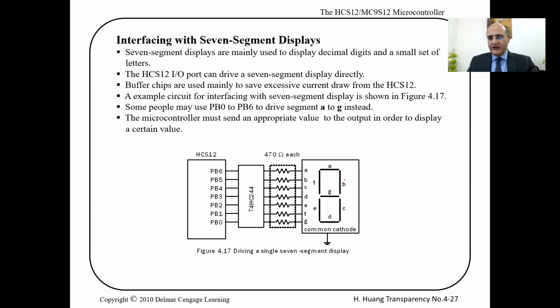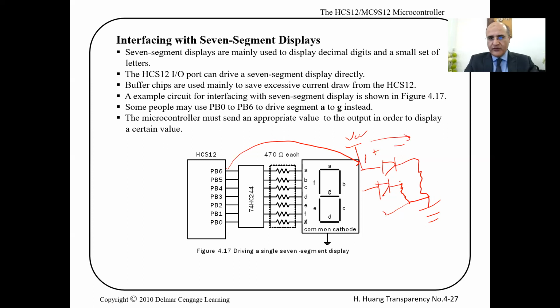I was talking before we ended the last lecture about this common cathode. All the LEDs over here have a cathode that is common. Now, when I write a 1 here, this means that I connected this to VCC on this pin. There will be a current that flows from the higher voltage to the lower voltage and thus turns on the LED. But what happens if I pull this to high, to VCC? There will be no voltage drop and no current. The LED will turn off, right?